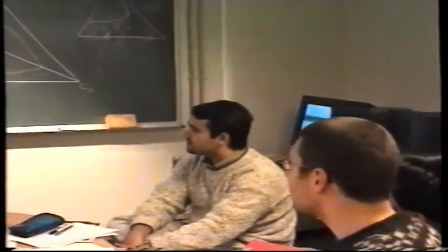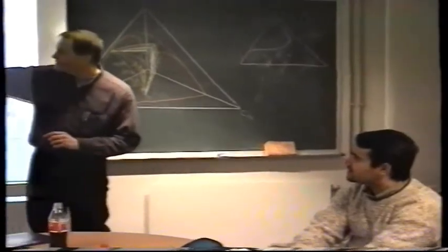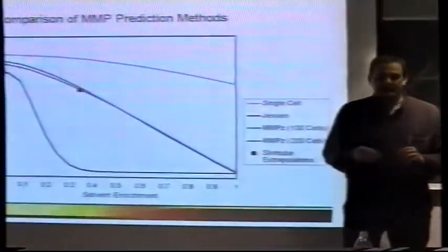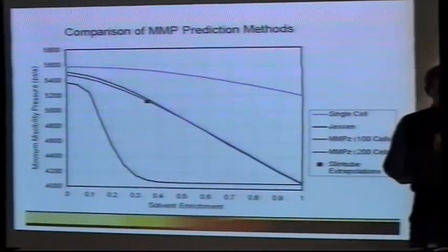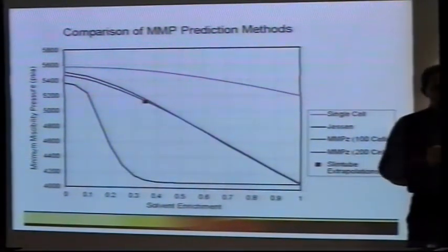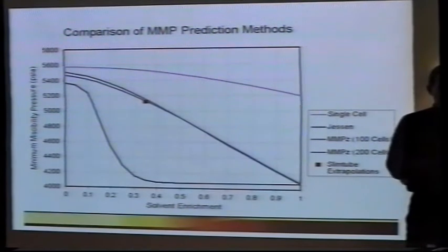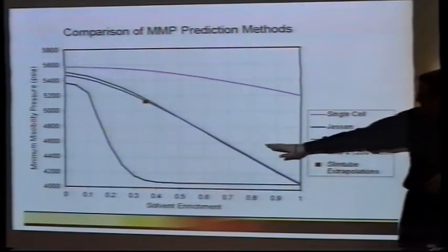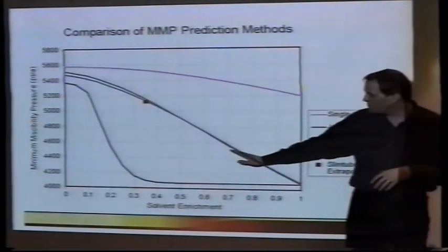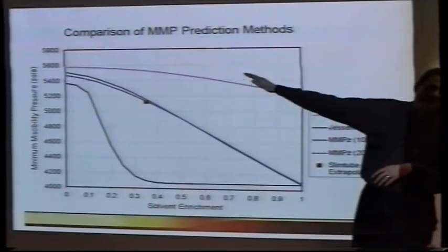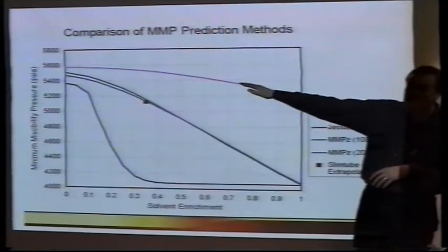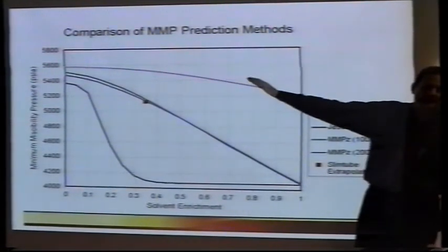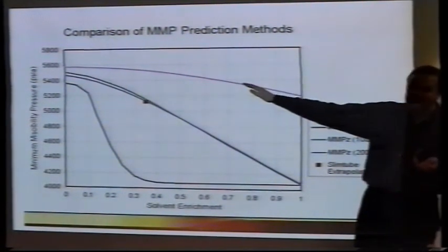Well, this one's the right one. This one is if you require that you eliminate any leading gas bank in your displacement, that you force it to go all the way from minimum miscibility conditions to minimum vaporizing miscibility conditions, this would be the answer. But you don't care that it's vaporizing.